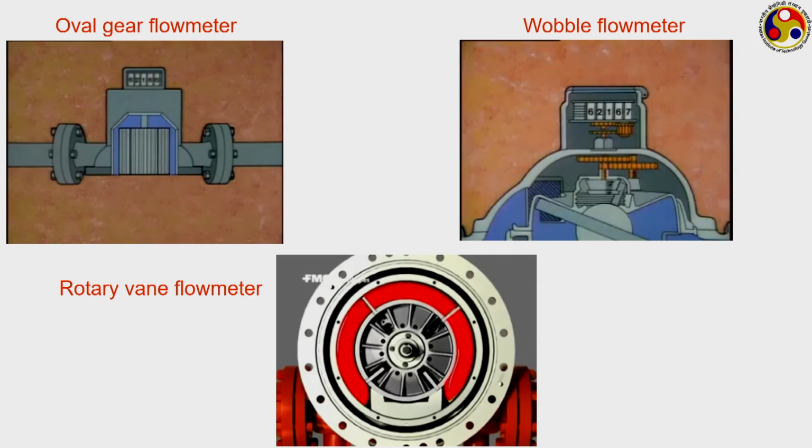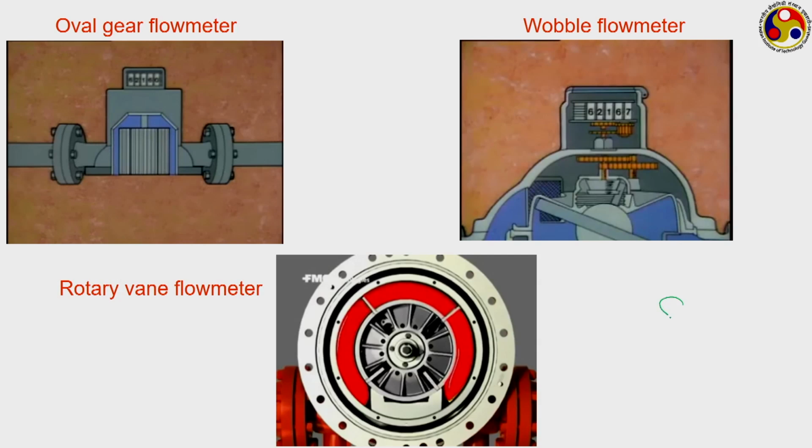We can have a few other variations also, like something coming to my mind is called the lobe flow meter, where we have 2 lobes of a particular shape, somewhat like a dumbbell shape, and as the fluid flows through this, the lobes form a mechanism quite similar to gears. So, this positive displacement flow meter has found extensive application, particularly in long term operation dealing with high viscosity fluids.